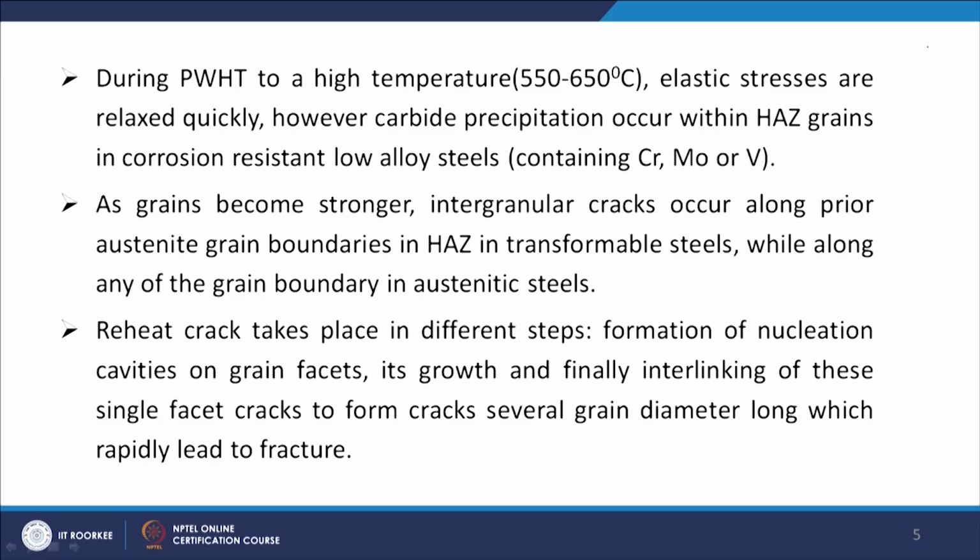Once they are interlinked, the crack will propagate, and that length will be several grain diameters long, which will lead to rapid fracture of the welded specimen. This way, in different steps, you have the failure taking place.